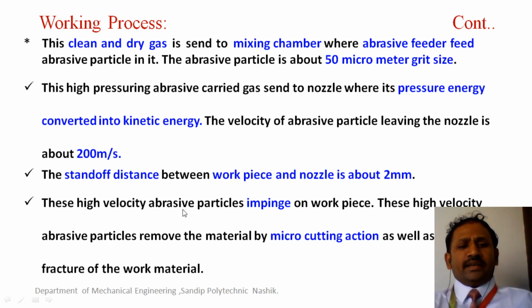These high velocity abrasive particles impinge on the workpiece. Impinge means strike on the workpiece. And these abrasive particles remove the material by micro cutting action, in the form of powder or some melting or evaporation. But in brittle material, it forms in powder form.